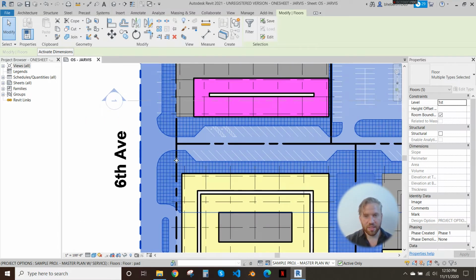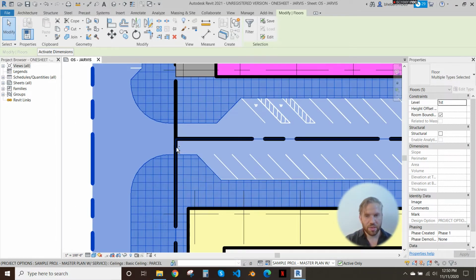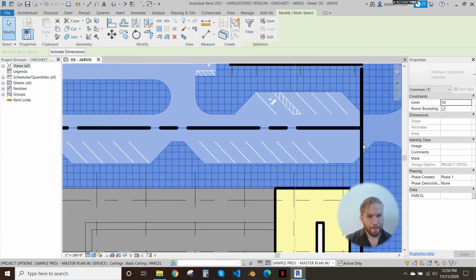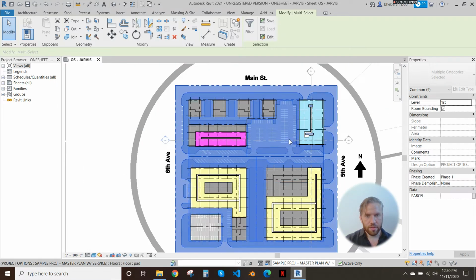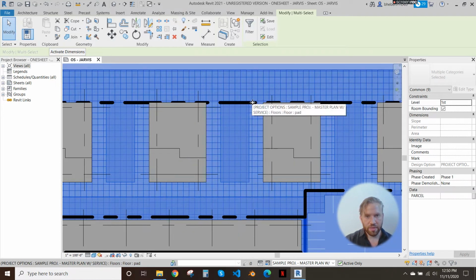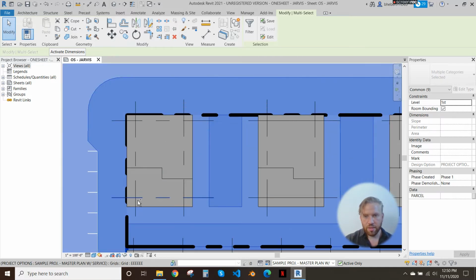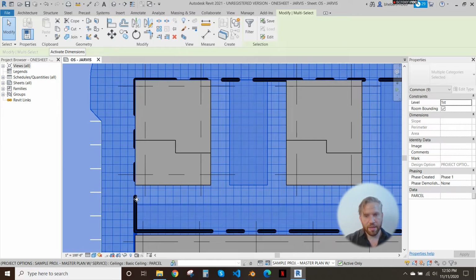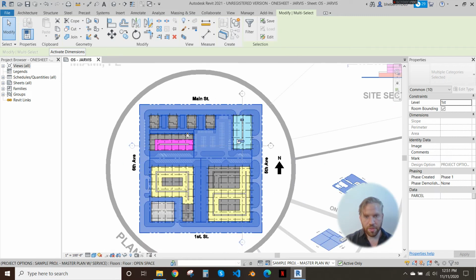Now we're going to zoom in on these property lines. These property lines are actually planes in here. They're not actually property lines. So one by one, we need to also select these, and you just kind of continue to zoom out to make sure you have everything selected. You may need to actually hold while you're hovering over. You can press the tab button to make sure you're selecting correct things. It kind of cycles through the draw order. So that's an extra little helpful tip there.